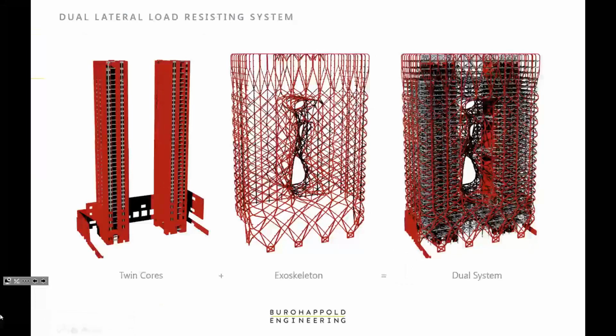So before I get into the computational engineering part of it, a little bit about the building. The structure is about 170 meters high. It's got 2 concrete cores, an exoskeleton, which is, think of a shell on a turtle. It's something that's giving rigidity and strength, and it's placed on the outside where, as you know from your studies, it's the most efficient.